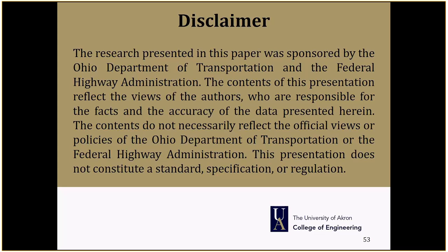That's the question. There are 2 things. One is the membrane rupture can cause leakage. And what we have shown here in this work is that's not necessarily a problem. So the rupture of the membrane is probably not causing the problem. In our tests, we found that even 1 inch of differential deflection, 1 inch of tension is not causing any water leakage at the joint.